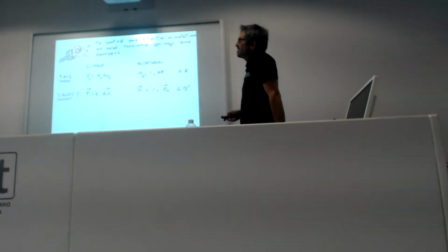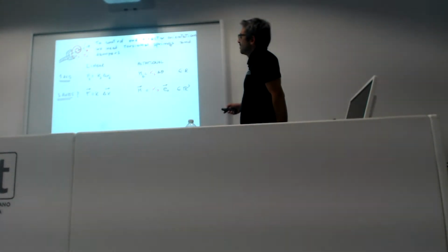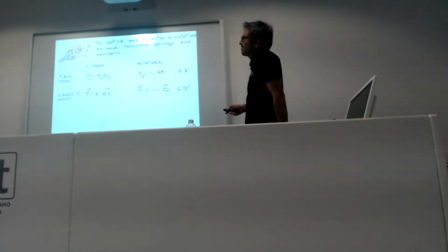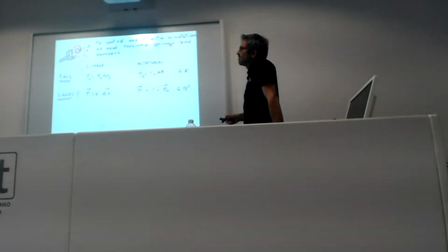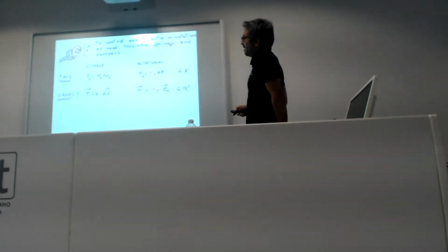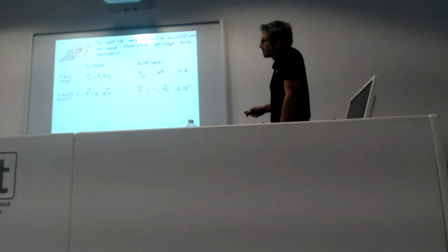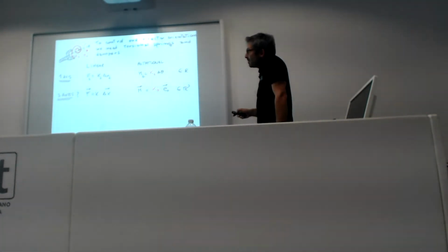If you have three axes, as in the linear case, we extend this to the vectorial form, and we have a 3D vector of Cartesian force equal to the stiffness we said in our controller times the error in position, which is also a 3D vector. But in the rotational case, we have a 3D moment.